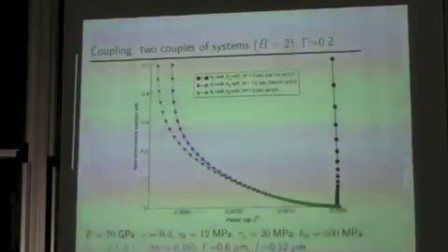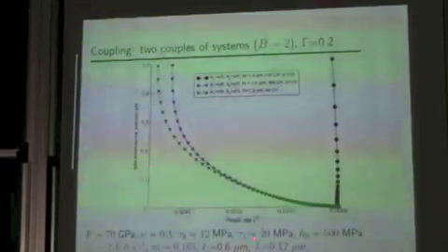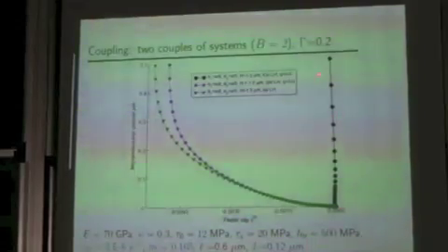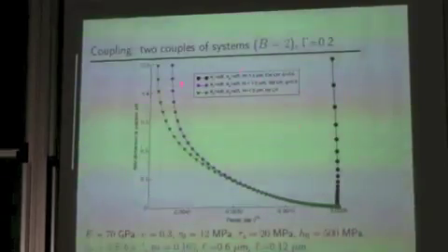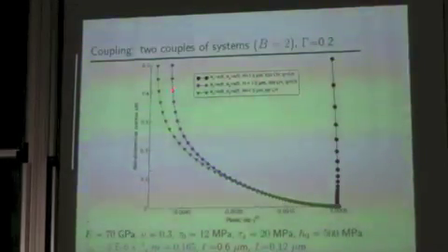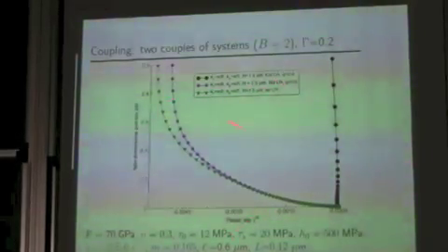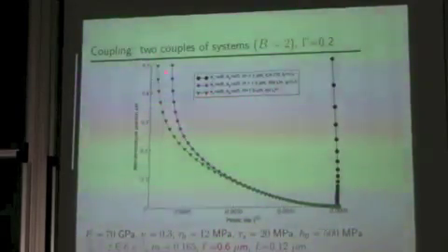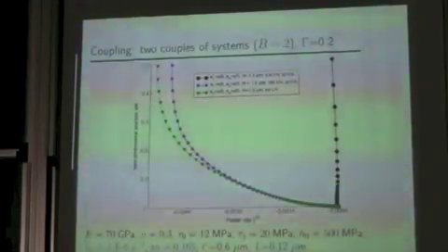And in fact, see, this is the plastic slip gamma 2, and this black curve is our new model, with all the gradient effects. This magenta plot is standard latent hardening, so you see the gamma 2 is even more negative, and the green one is no latent hardening at all, and this effect is just due to the coupling due to the dislocation density, the Nye tensor, in the defect energy.